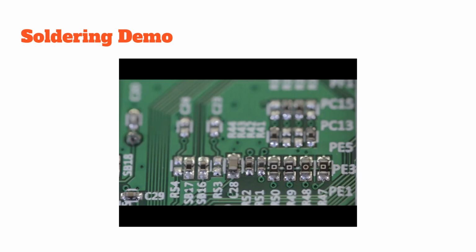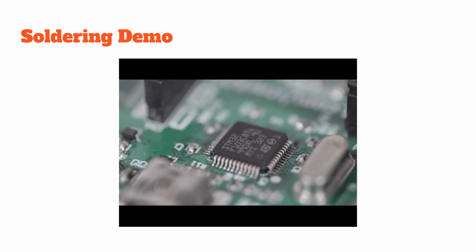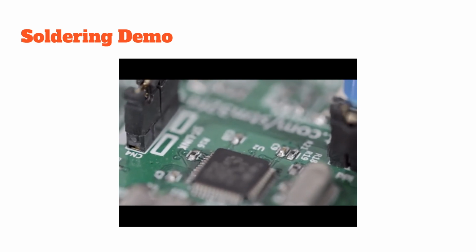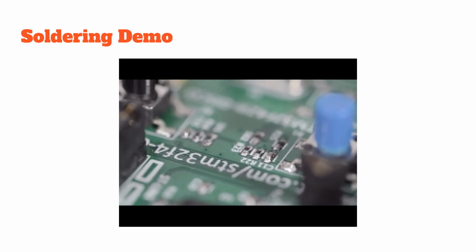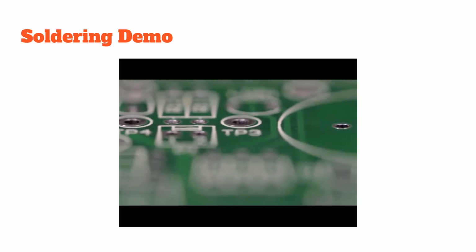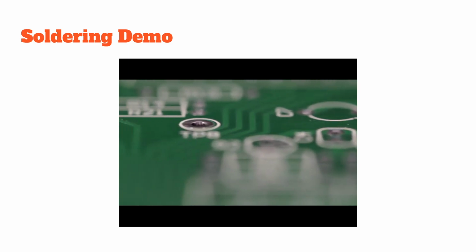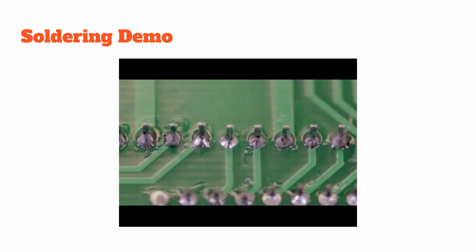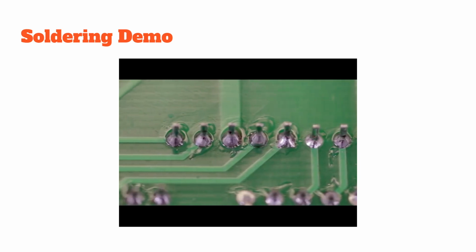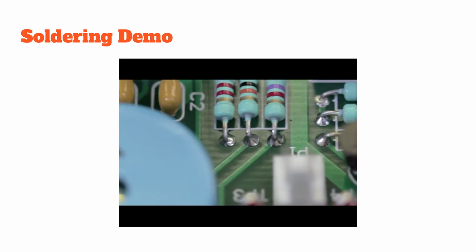There are two different soldering types, surface mount and through-hole. Surface mount connections are made by heating components with pre-applied solder in an oven so that it melts and joins to the surface of the board. For this tutorial, we'll look at plated through-hole soldering, which is done on boards with printed circuits on both sides. Through-hole soldering is when components are pushed through a hole in the board and soldered from the other side. The solder flows through the hole to make the best possible contact.